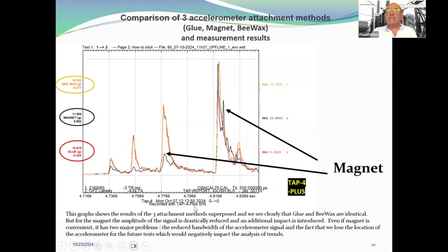I think with these three tests that have been done, I have seen also a publication from B&K, which is a manufacturer of accelerometers, showing that according to the method of attachment of the accelerometers, you are going to get different bandwidth for the quality of the signal. So in fact, it's why we are using the glue for the attachment. It has a lot of benefits. The magnet is, well, easy, but it's problematic.